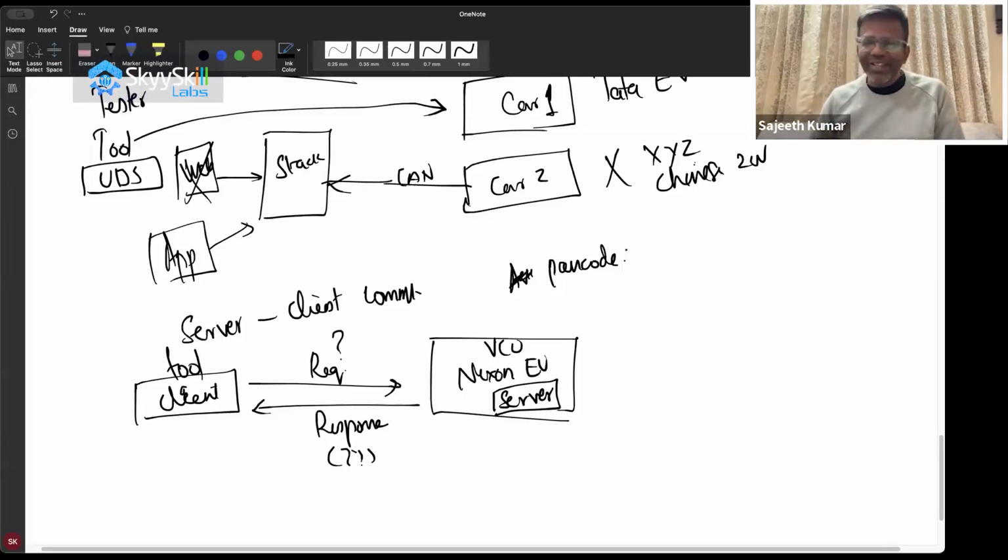And even when they exchange messages, suppose it's saying vehicle speed, right? So this will say vehicle speed is 1425, right? Now, what in the world does 1425 mean? Is it 142.5 kilometers per hour or is it 14.25? Because all the CAN messages work on fixed point arithmetic, right?